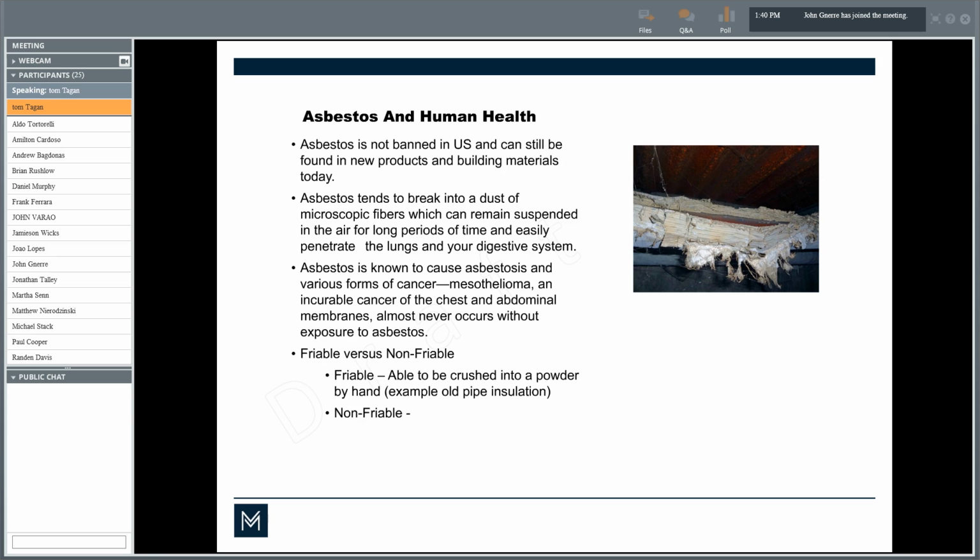The key component to understand about asbestos, and this is critical for you to understand, is there's a real difference between what is called friable and non-friable. The friable material is basically material that you can, with your hand, crush into a powder, turn into dust. The non-friable is essentially everything else. So when you have floor tile or a mastic, the material that's underneath a floor tile that contains asbestos, unless you break them apart, those materials simply do not release asbestos. In the case of the mastic, it's like having a tar, and these little fibers are tied up in the tar, so it's very difficult for them to get into the air. So your exposure to mastic is nowhere near the same thing as being exposed to things like pipe insulation that is now in a powdery form.